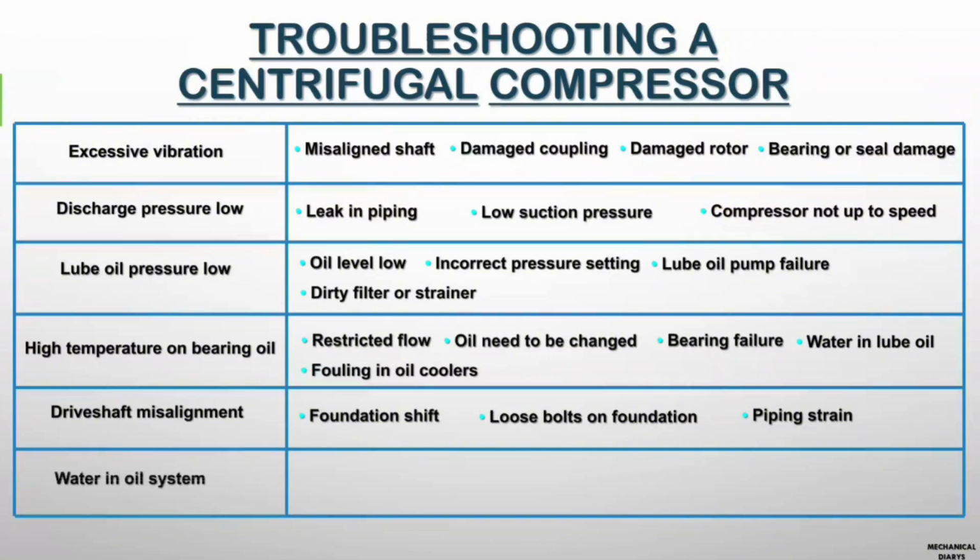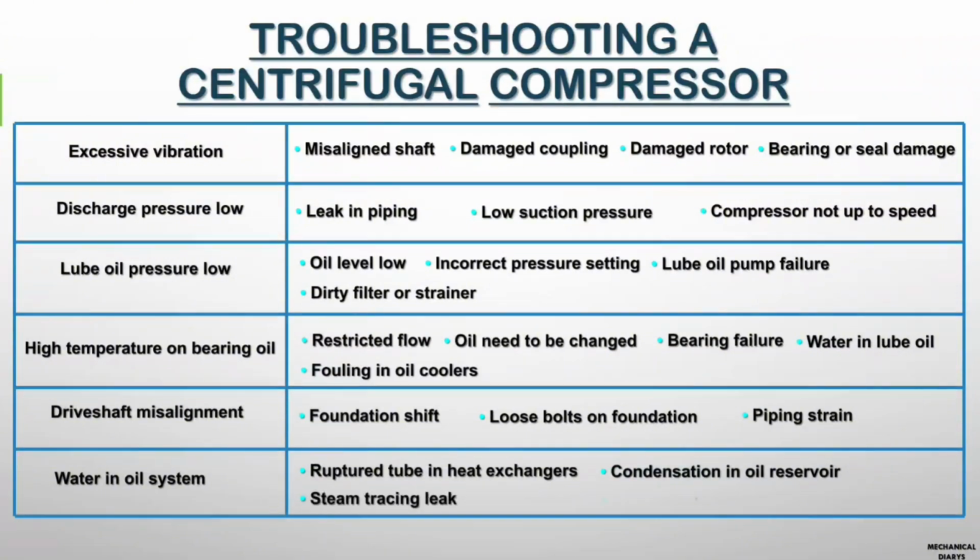Finally, the water and oil system. There are four reasons water will mix with the oil system. One, a before-cooler tube leak, which means an exchanger tube leak. Then condensation in the oil receivers, a steam tracing leak, and last, sometimes rainwater falling on the oil tank.